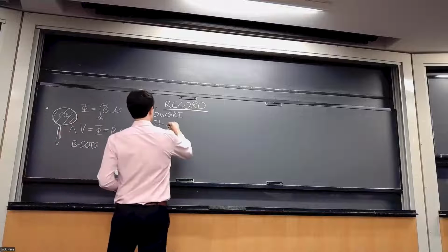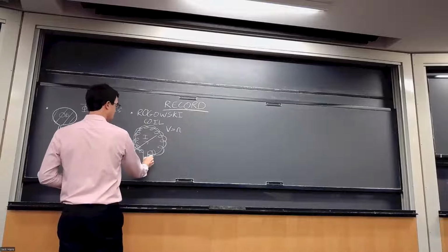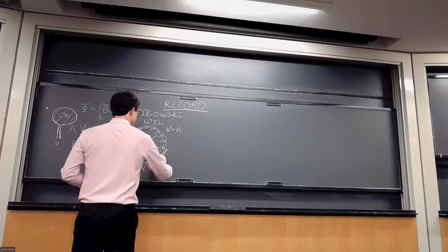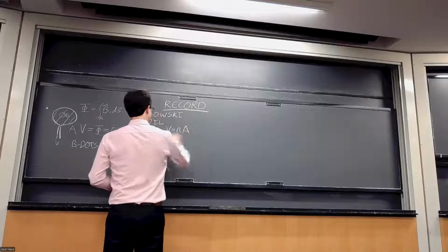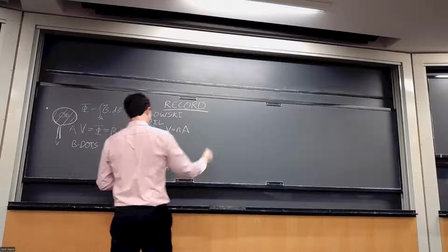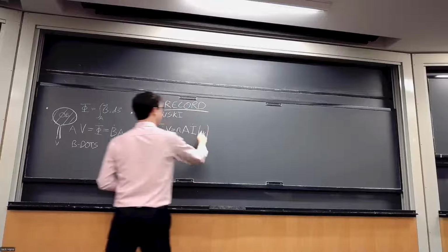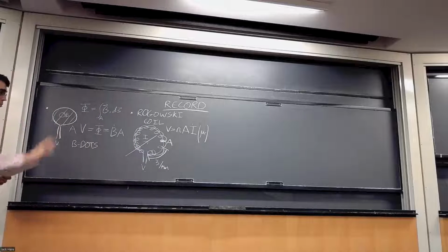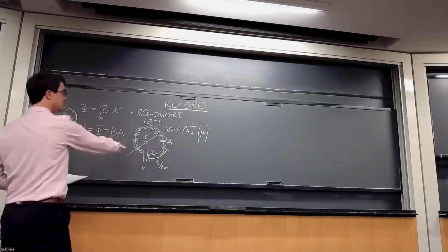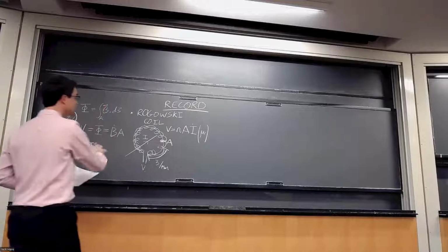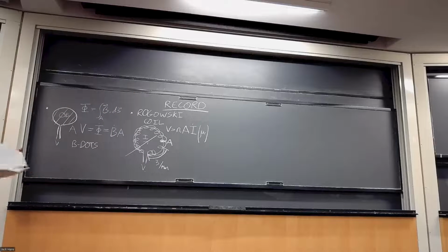And we found that the voltage that we get out here is equal to the number of turns per unit length. So, for example, this might be 3 turns per millimeter. The area of each of these little loops here times I dot, and there was an optional factor of mu r here if this is different from 1, or if it's different from 1 because you've chosen a material that saturates, like steel or something like that. So these Rogowski coils are used for measuring current in a very similar way to B dots. We get out a voltage, which we can then integrate up and find the current.